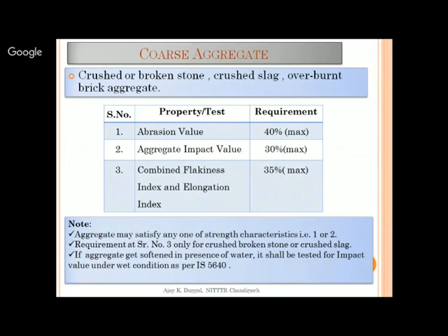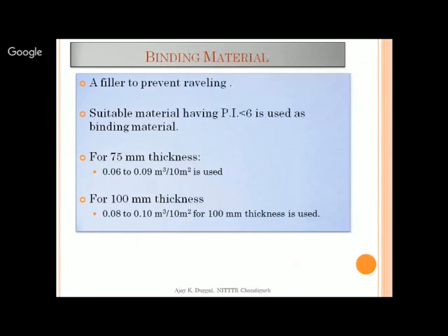And so that the aggregate can be compacted well, the parameters of elongation and flakiness have to be kept within control, and the combined values of them should not exceed 35%. So you will have to certify that the aggregate meets this requirement, and the fine material meets the requirements of plasticity index and liquid limit. Now I need to know how much is the quantity of screenings required.